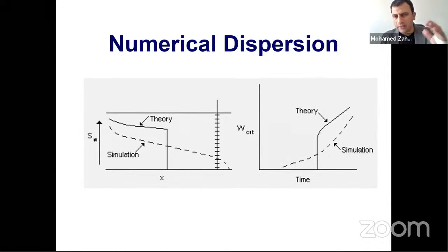For example, when the geologist calculates, he doesn't predict the change of saturation or the change of Bo, which is the fluid properties, with pressure over distance. He uses one parameter everywhere, or for example interpolated parameters. But in the simulation, you calculate each fluid property depending on the pressure. Because the pressure, as simple as that, increases with depth.